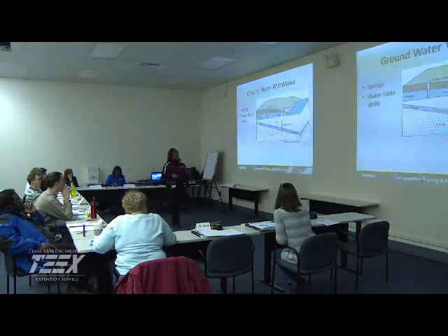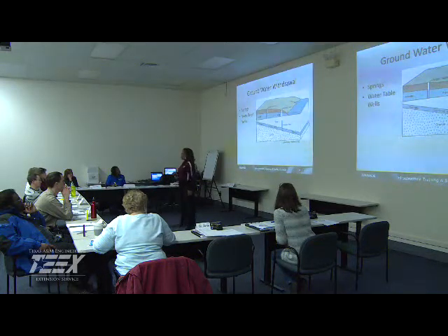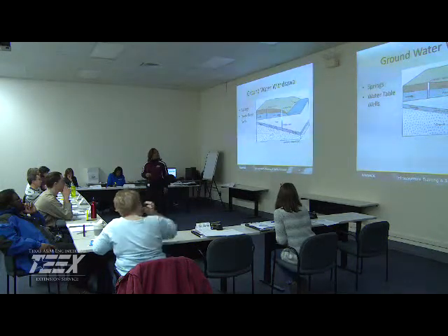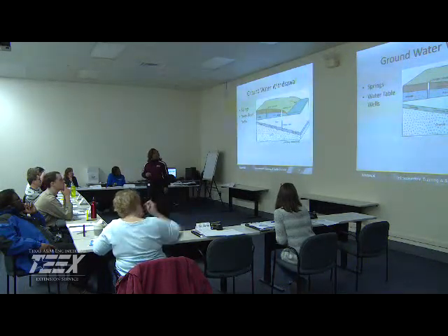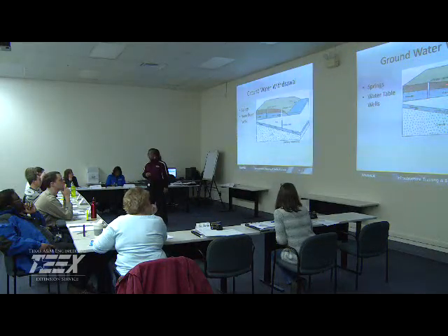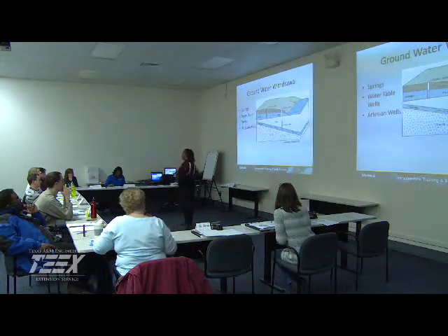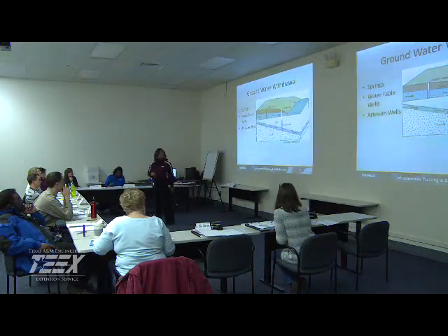We have water table wells, which are your shallow wells, usually 50, 100 feet. Usually you don't see the shallow wells deeper than that. And so they are not confined from above with anything. So this would be like a water table where all you have maybe would be sand, gravel above it. We have artesian wells, which are confined aquifers or overlaid by an impervious layer. Usually they are under pressure, so when you tap down into that, that water will rise all the way up to the top also because it's under pressure.